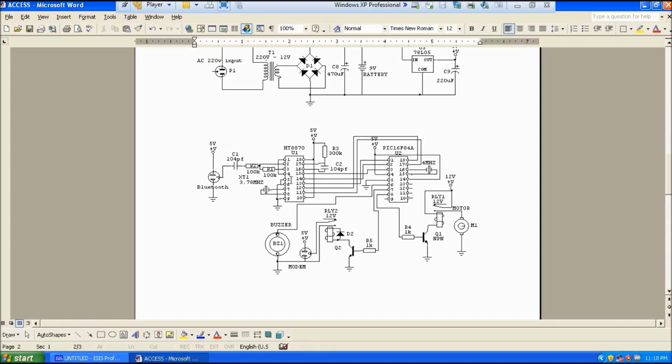So when you press 1 on your mobile phone, it's received by the Bluetooth module here. The Bluetooth module sends it through the capacitor, which filters the tone. The combination of the resistors reduces the audio level, more like a voltage divider.